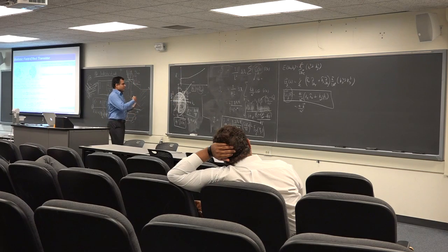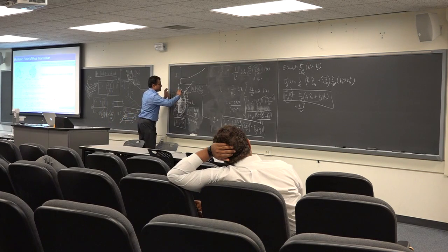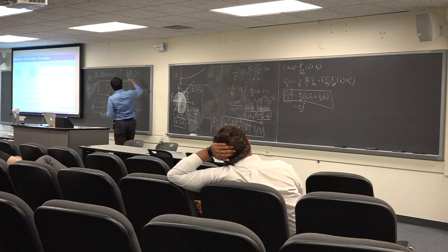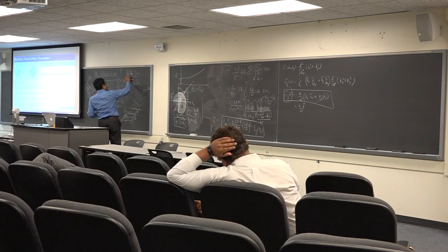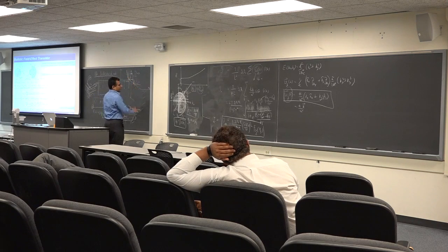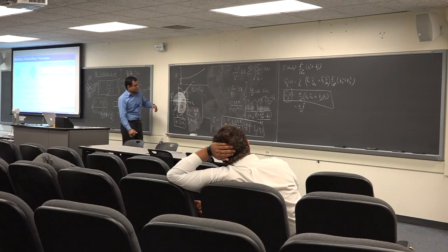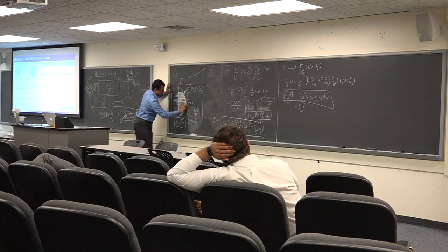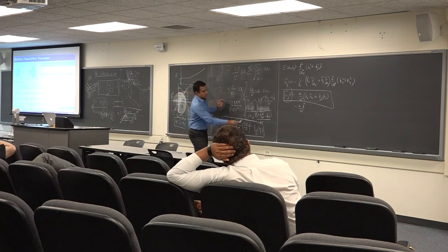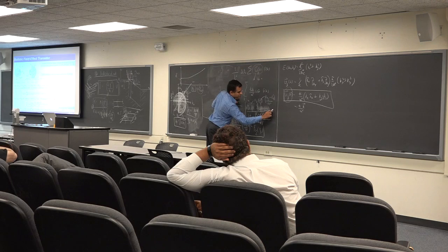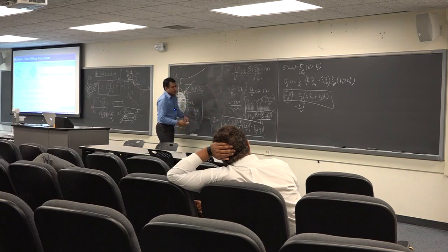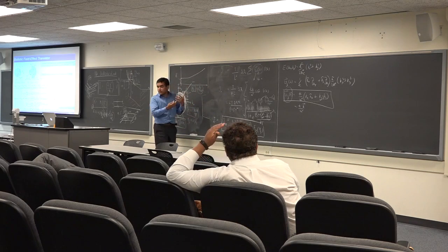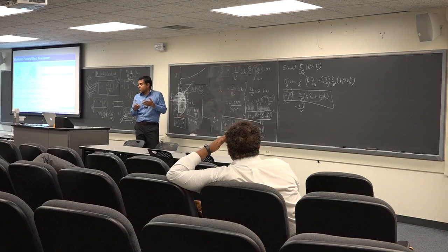And now when you connect the electrodes, again, just like for the 1D conductor, you had a right-going Fermi level, which was in equilibrium with the source, and a left-going Fermi level in equilibrium with the chemical potential of the drain. Similarly, the right-going Fermi level here, which is this term, becomes your mu, or Fermi level of the source or the left contact, and for the left going, it becomes that of the right contact, and the difference is the total current. Okay? So the difference is the total current.